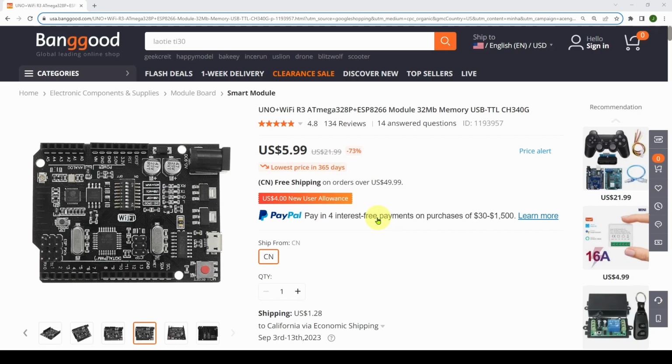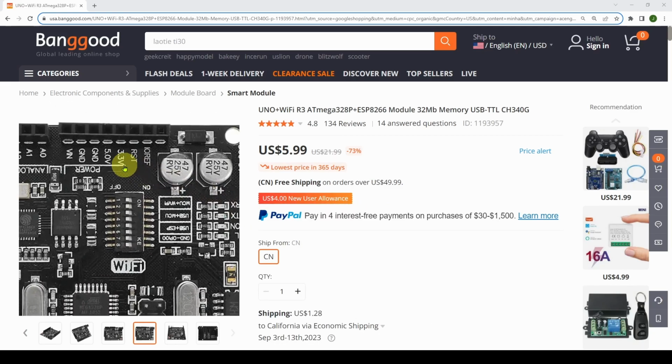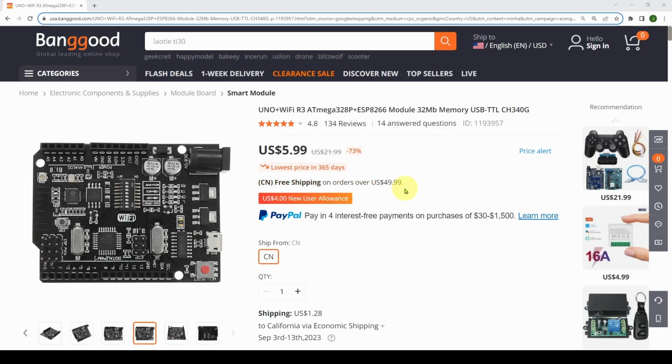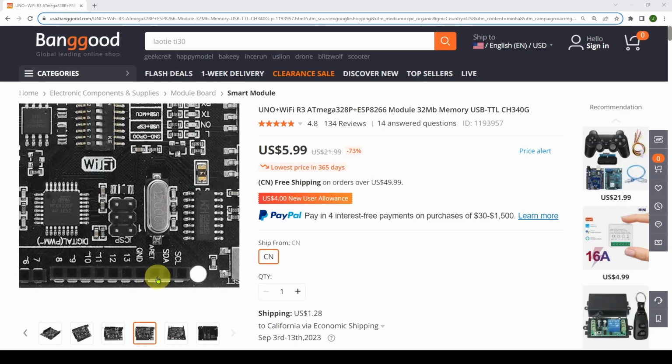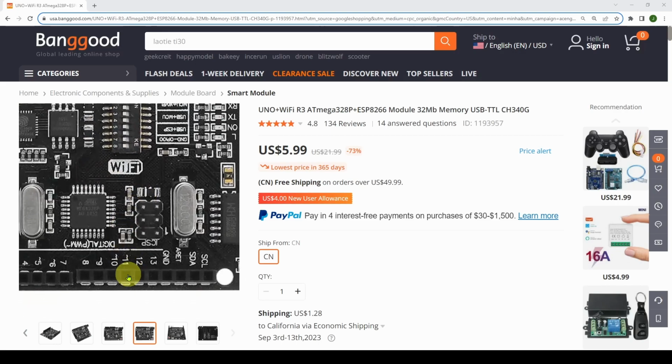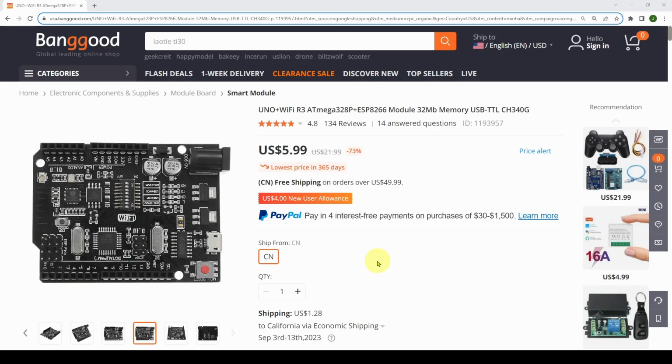In this video, we're going to look into a little bit more depth. We're going to show you how that C# application can talk over Wi-Fi and directly access the GPIO pins. And we're going to show you how to write some sketches for this to do that. And we're going to show you how to tweak the existing C# application we developed previously so that it can talk directly to the GPIO pin. So basically we're going to use sketches and C# applications we developed before with some minor tweaks to allow you to actually access these GPIO pins.